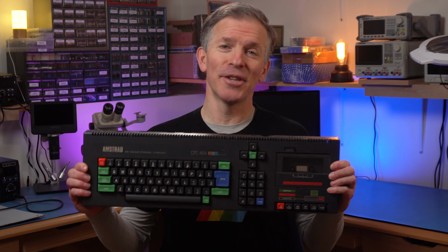Confusing enough for you yet? No? The Amstrad CPC just entered the chat. Amstrad engineers decided that it would be a good idea to go against the normal use of the Z80 and, drum roll please, use the top byte of the address bus to access different chips. Why? We'll see that in a second, but let's have a look at what it actually means.